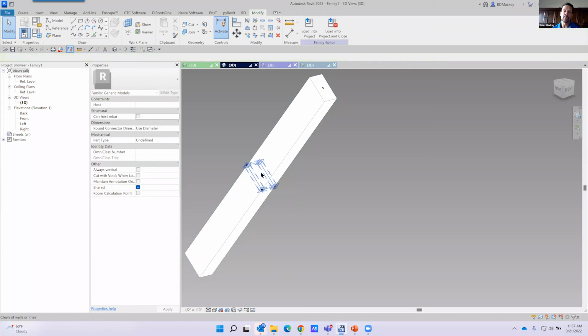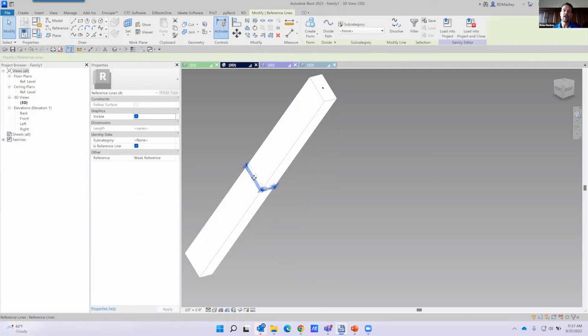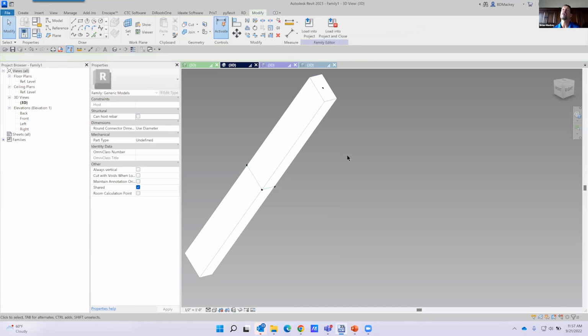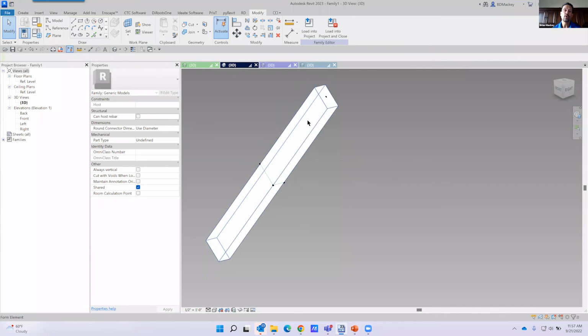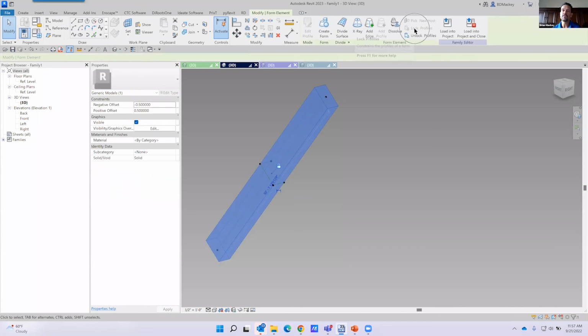I had done this and I had parameterized the little profile here. And when I changed the parameterization of this, since it was just a sweep in this case, it only changed it where the lines were, not at either end. And I was like, oh my God. So I was making all these sweeps crazy with 2 points on it. Those 2 points then were hosted at the end. And then I realized that if you use reference lines, it's locked by default. If you don't, it's not.